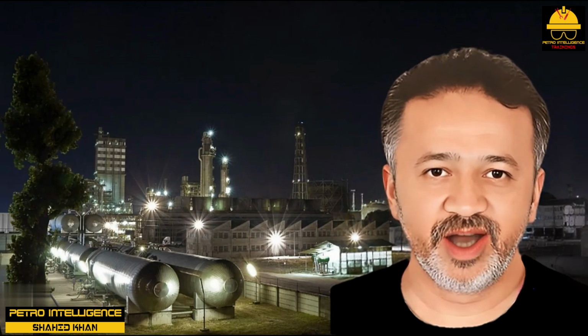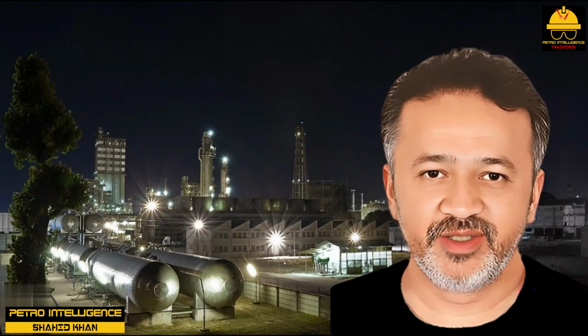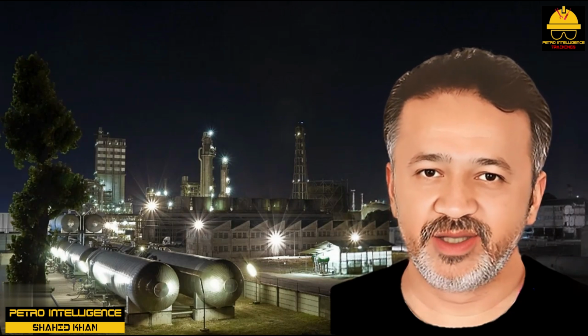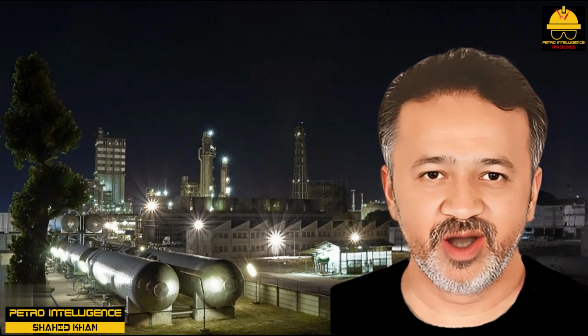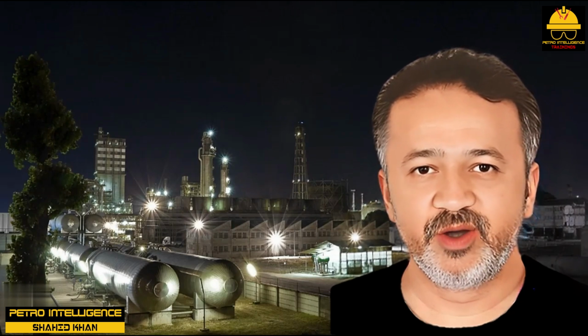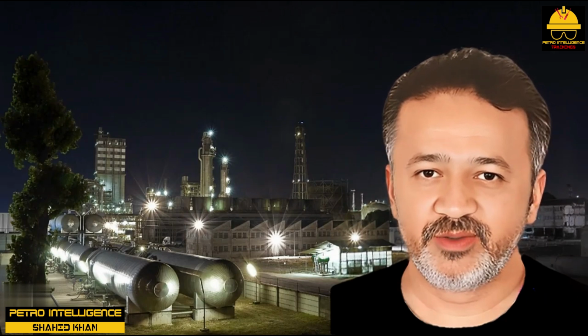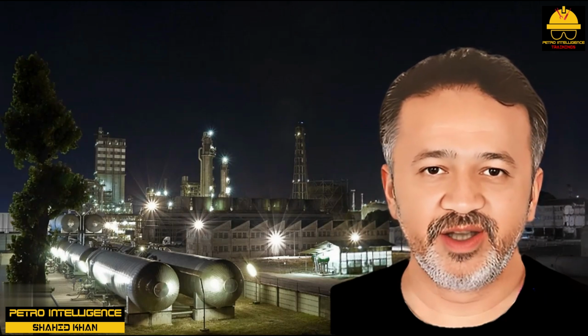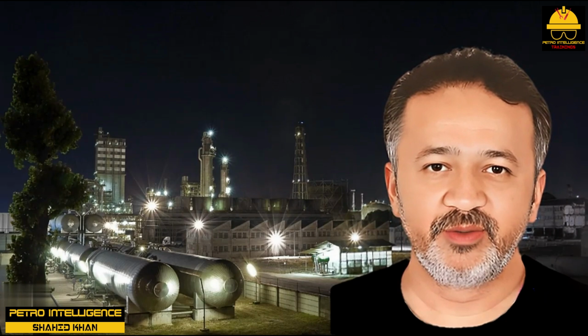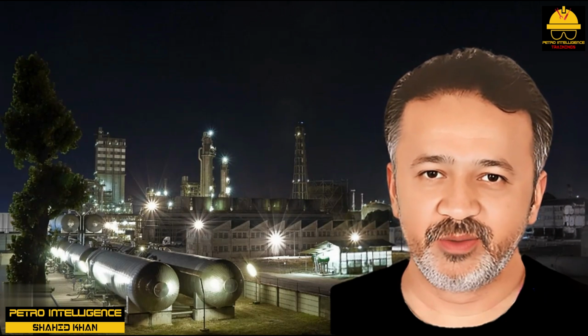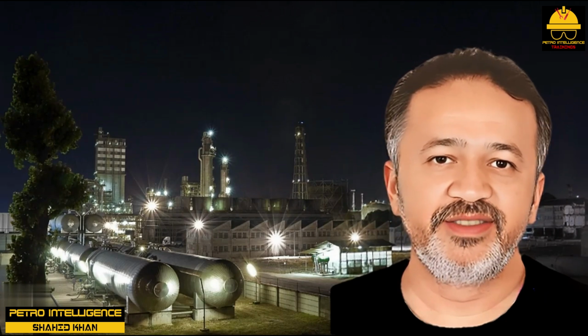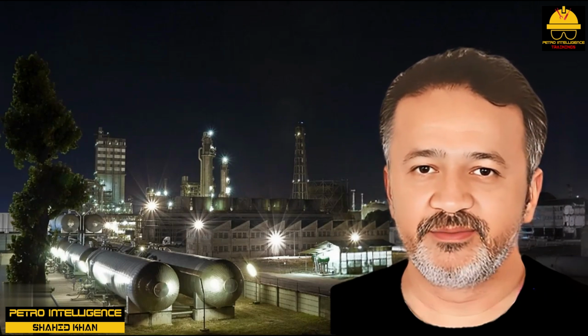A delayed coker operates with a zero-order reaction. This means the rate of reaction depends on time in the coke drum and the temperature in the coke drum. The composition of the products of reaction has no effect. On the other hand, hydrocracking is exothermic. The consumption of hydrogen liberates heat in the hydrocracking reaction.